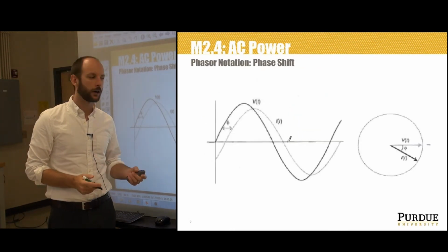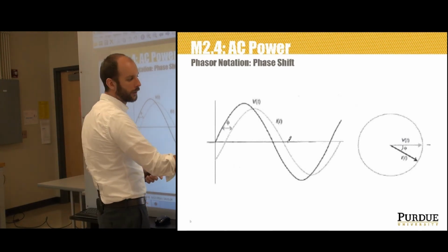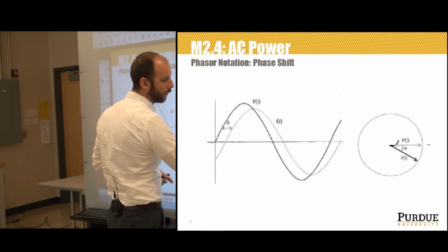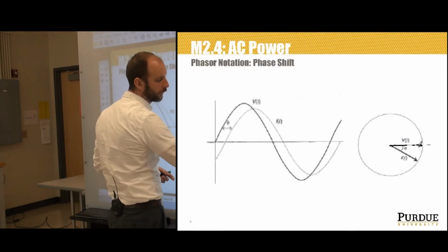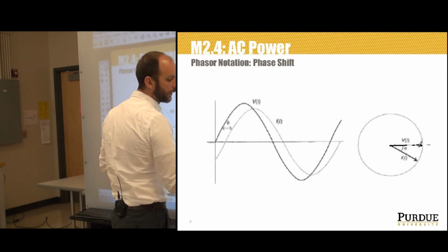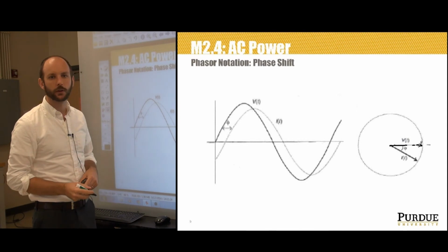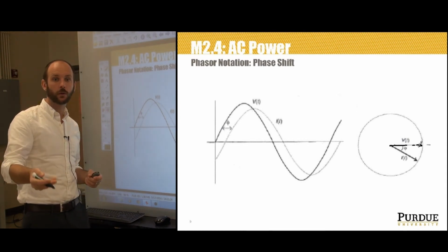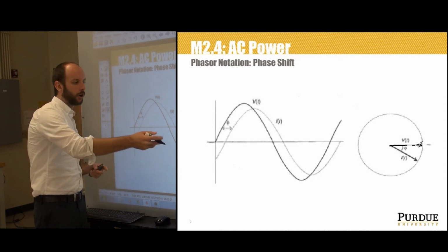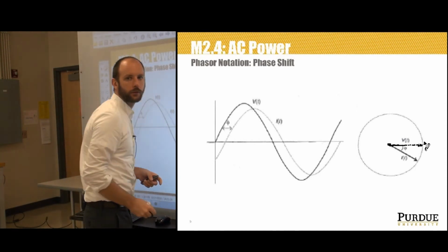On the phasor diagram, which we're showing down here on the right, phasor diagram just refers to a picture that represents voltages and currents as phasor quantities. Here we see V of t is the reference phasor, and I of t is referred to the reference phasor. So on the phasor diagram shown down here, we've drawn the voltage as an arrow extending from the origin along the real axis, right? It extends from the origin in the positive real axis.